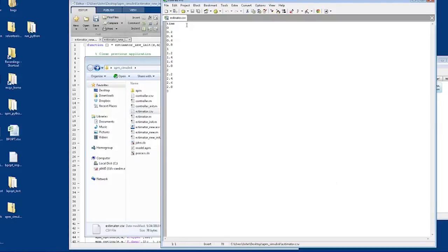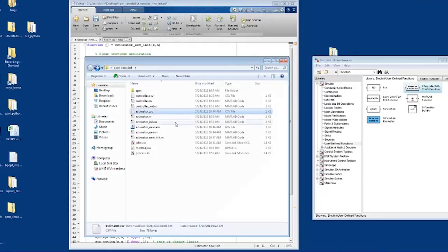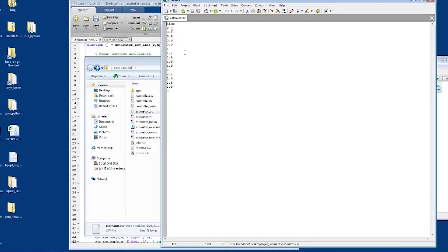You could also put in, let's say you had U values over that time horizon, things like 1, 2. It's just a CSV file. We're just going to specify the time in this case. The U values are going to come from the Simulink model. I'll close that, and the other thing that's important is this interval here, 0.2 seconds, matches your triggered subsystem, so that Simulink is executing this every 0.2 seconds in the simulation. It agrees with your time horizon that you have in your data file.